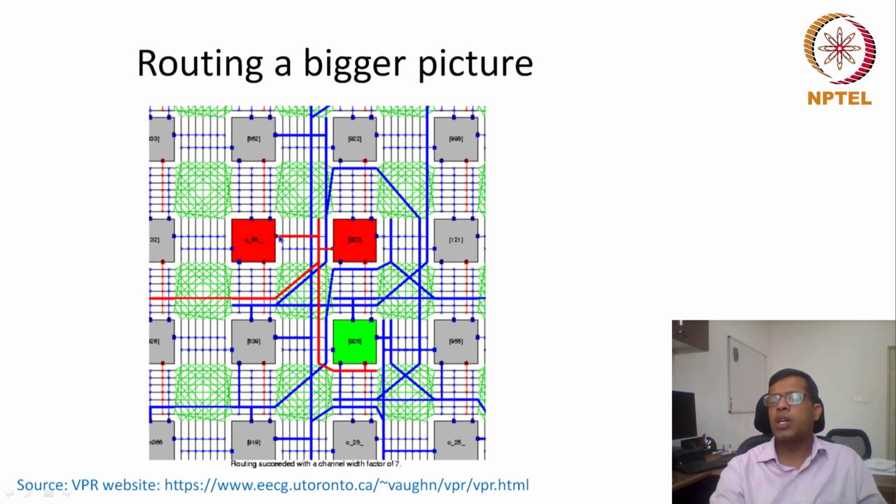Because of these configurable connections, any logic tile or CLB can connect to any other logic tile or CLB. Sometimes we will feel that the number of channels, number of wires, or the number of inputs and outputs in connection switch boxes could be quite large. Okay, but that's the requirement for programmability.